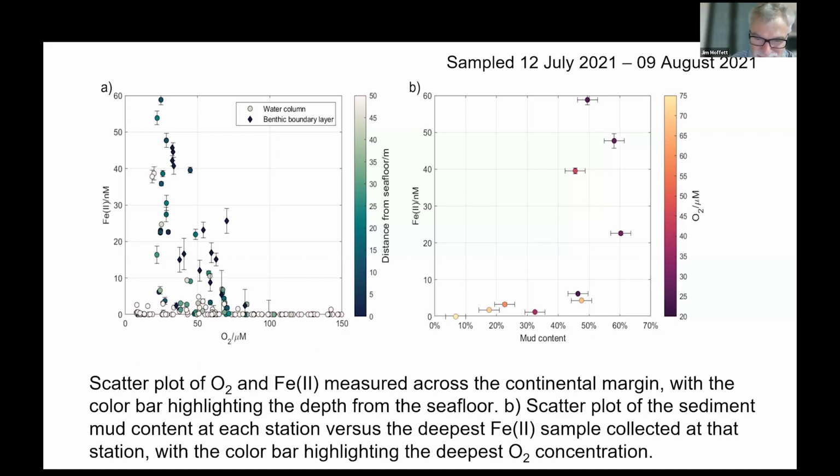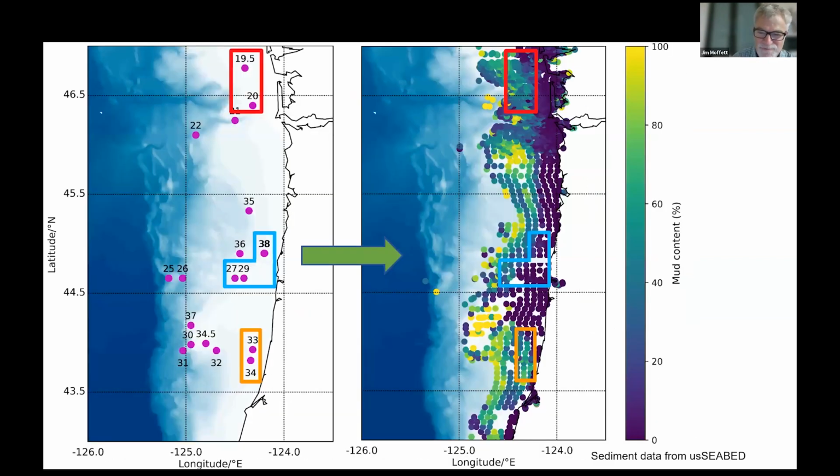These models, by the way, explicitly look at carbon oxidation rates because that's a very effective way to study nutrient dynamics in these systems. Carbon oxidation releases nitrogen, for example, from organic matter at the sediment water interface, and that's very important. But you can have a lot of carbon oxidation releasing iron, and if the bottom water oxygen is high, that iron gets oxidized and reprecipitated fairly quickly. That's why bottom water oxygen matters so much.